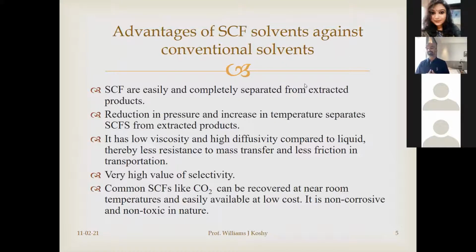As we say, in distillation also the term selectivity is generally used, as relative volatility. If the relative volatility value is 1, distillation separation is not possible. If the value is slightly greater than 1, distillation is possible but difficult. The greater the value from 1, the easier the distillation will be. Similarly, the higher the selectivity, the easier your operation becomes.